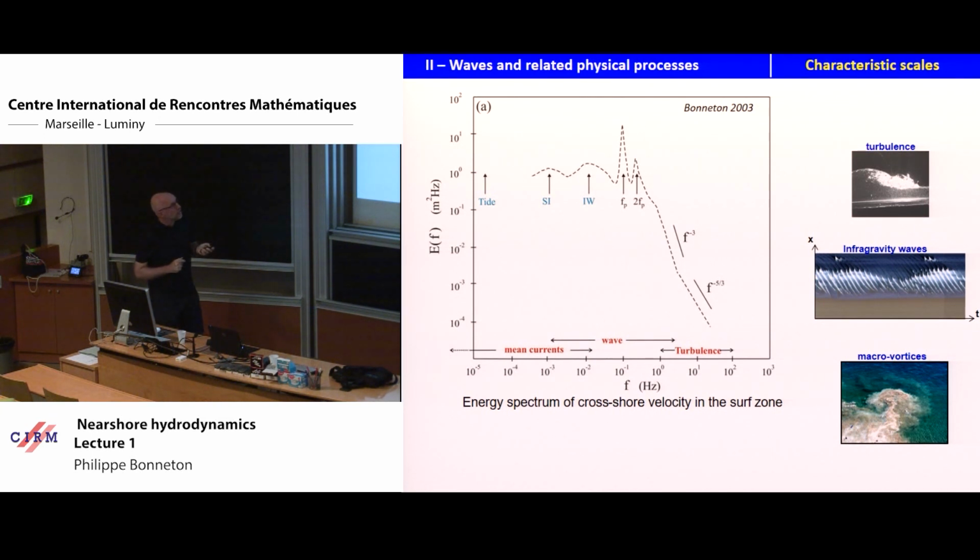And you can see the presence of infragravity waves, long period waves, just before the breaking, and also in the swash zone. You have a strong modulation of the wave field, and this process is due to nonlinearities of the shortwave field.